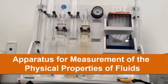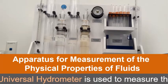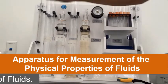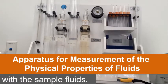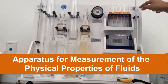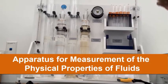So we will show each of the instruments that we are going to use. This is the universal hydrometer, which we use to measure the specific gravity of the substances. And these are the hydrometer jars. We have two, one for the glycerin and one for the castor oil as our samples. At first, we'll fill them with water. Then we'll insert the universal hydrometer into the jars.